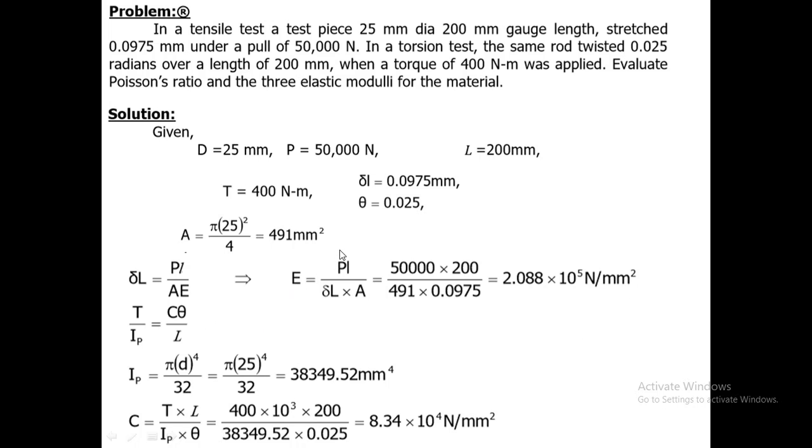So this is the first part of the problem where the tensile data is given, and using the tensile equations, elongation and all those things, you can calculate the Young's modulus. Young's modulus is related to the tensile test, when the rod is subjected to tensile forces. The normal stress by normal strain is Young's modulus.